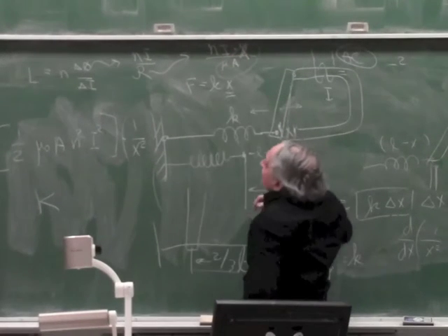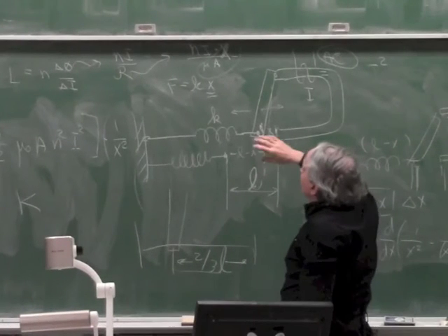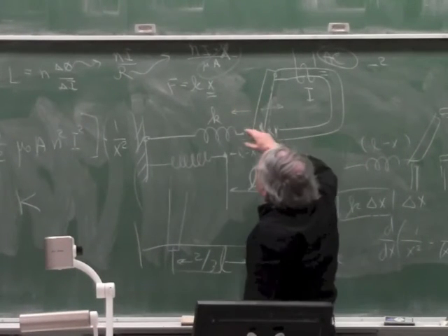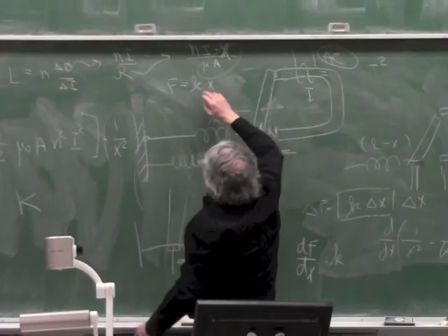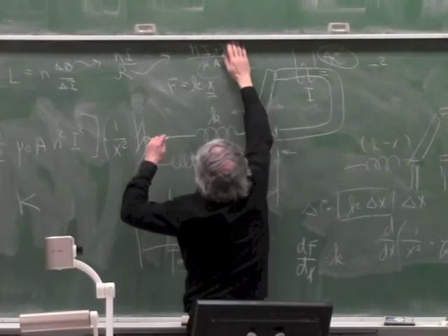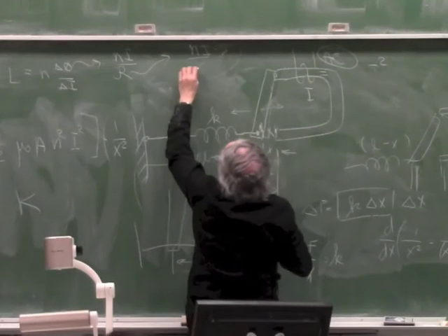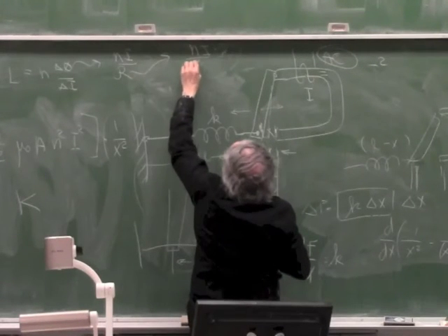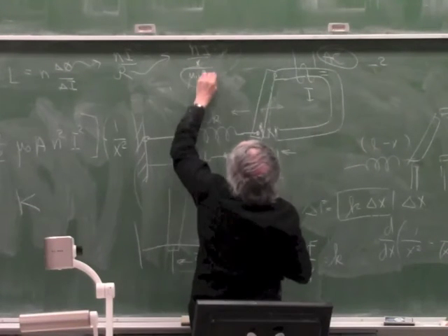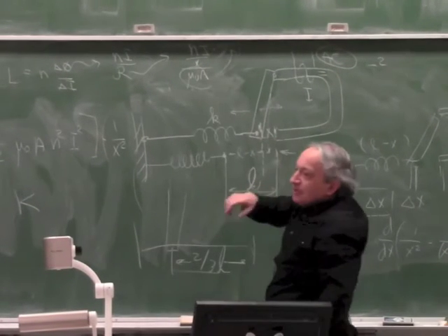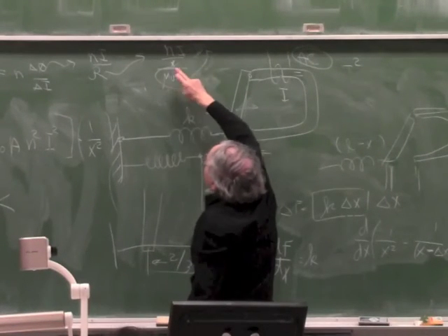So now the inductance will go up with like 1 over x. Sorry, I have to divide by that, it just changes. It's Ni divided by reluctance, and reluctance is x over mu 0 A, so mu 0 A goes to the top, so I'm getting the same thing you had one page ago, that it's Ni times this divided by x.